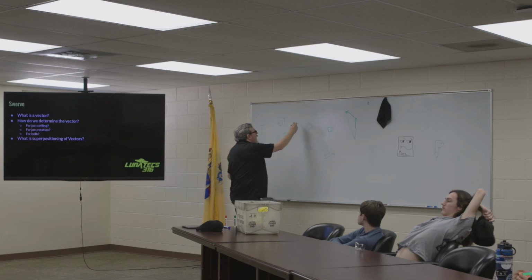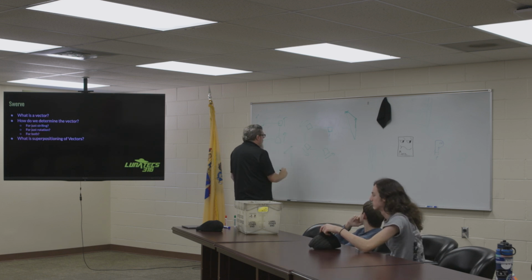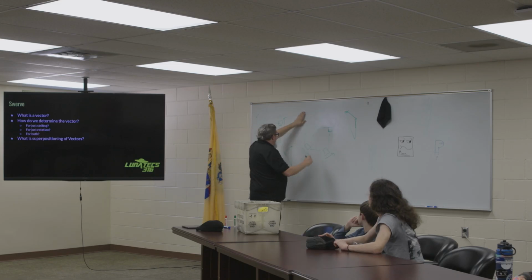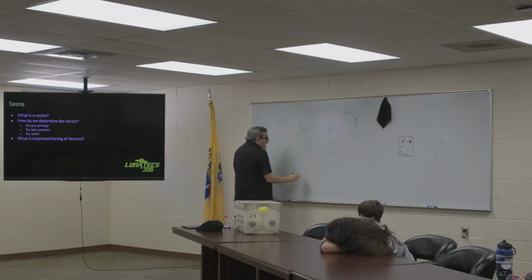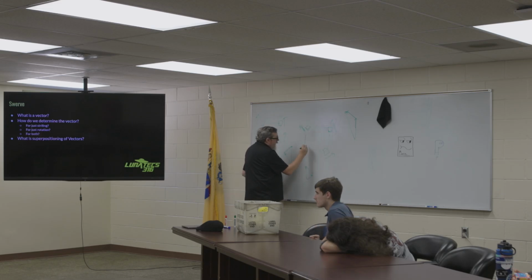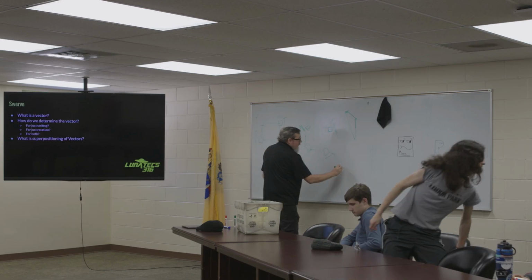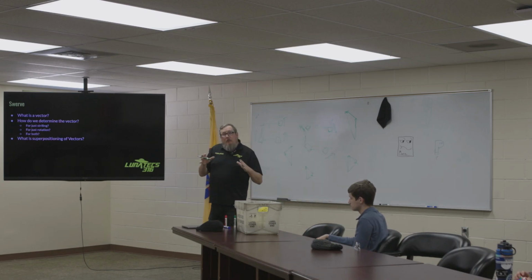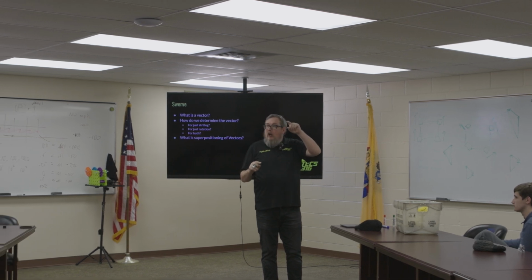I want to calculate this vector. So I'm going full speed and I'm going, okay. So I calculate again. I figure out this vector. So I turn the wheel to go, this is slightly more, this is slightly less. I want to calculate this one. So now I'm going to orient my wheel this way and send power that way. I want to do this one. So it's close to that. What ends up happening is I learn how to position my wheels by taking the two vectors that are dictating what my position should be and the speed I want to go at that direction.